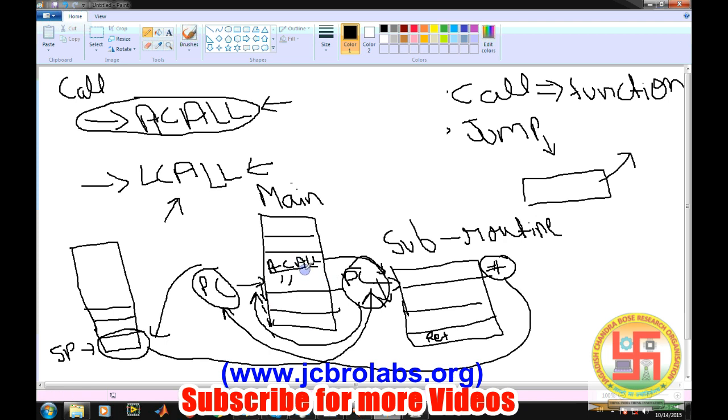In a call, the next address, or the content of the program counter, is first stored on the stack, and the address pointed to by the ACALL is loaded into the program counter. Then the program counter starts executing the instructions of the subroutine, and at the return instruction, whatever data was stored on the stack is fetched back and stored into the program counter.